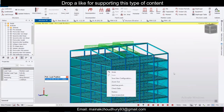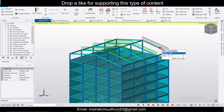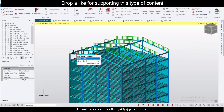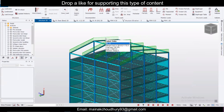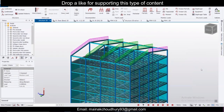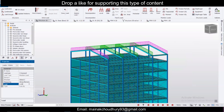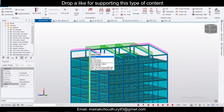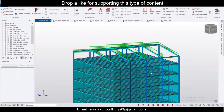2 kilonewton per meter we are providing here, 2 kilonewton per meter, and then 2, 2, and also 2. Another thing you can do, if you want to provide 1 here, you can just select, click on this and assign it first. Okay. And after you assign it, just press escape and then control and select all the portions which you want to change. Then you set this as 1. Okay. So like this also you can do, you can see the magnitude has been changed.